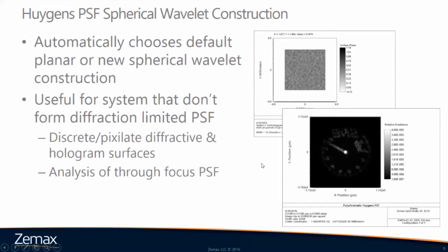The last feature I want to talk to you about today is a new wavelet construction method for the Huygens PSF in sequential mode. So previously, the Huygens PSF calculation always used a planar wavelet construction method. And this method works very well for optical systems that are forming a diffraction-limited point spread function.